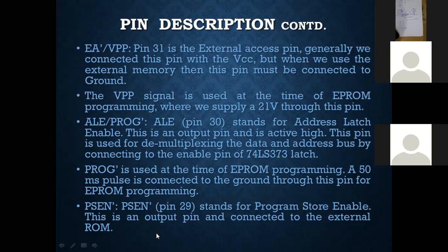That means whenever you have written some program in the simulator and in the hex file, and subsequently you are writing the program onto this, just like writing on a CD, you are burning the CD. Similarly, whenever burning this microcontroller, a 21 volt supply is to be given through this pin.